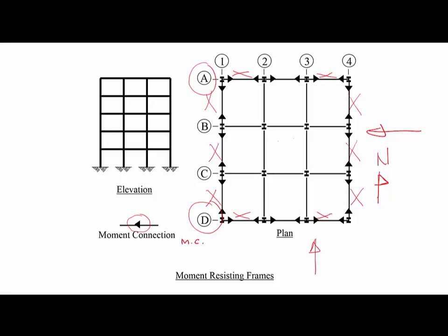But if we need to make sure that the exterior is going to be clear with no obstruction, then we need to remove the brace frames and use moment frames all through the building, and this way we have wide open areas all around the building.